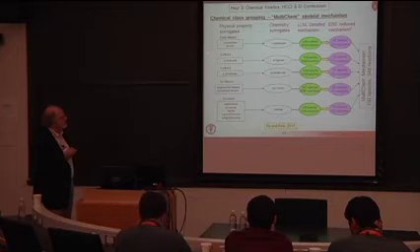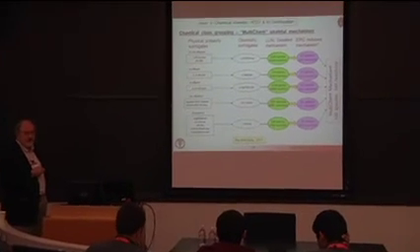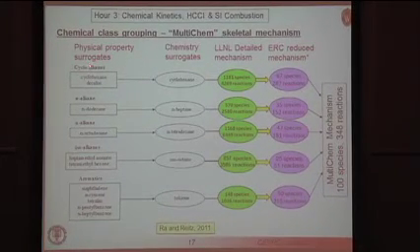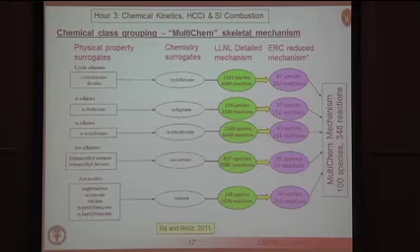So for example, I'm going to be talking about vaporization processes next when we meet tomorrow. We're going to try to have fidelity in matching the distillation curves and the properties of the fuels. We're going to have physical property surrogates that represent the cycloalkanes, the N-alkanes, the isoalkanes, aromatics, and also biofuels and so on. So those will be the physical properties, and that's relatively easy to identify because many of these species are well characterized in the literature. Their physical properties are well characterized.